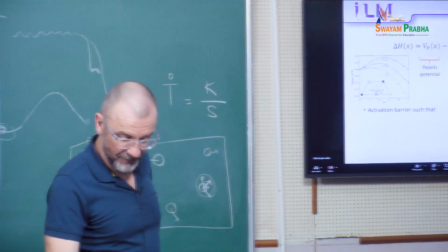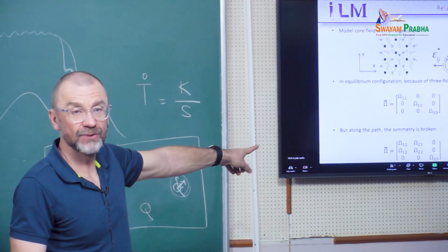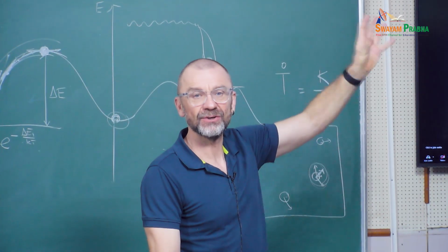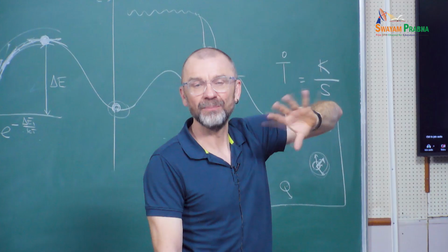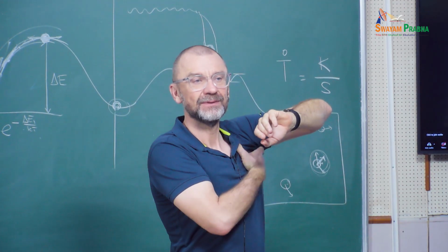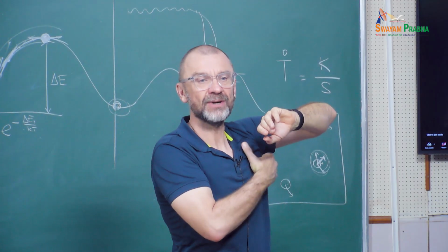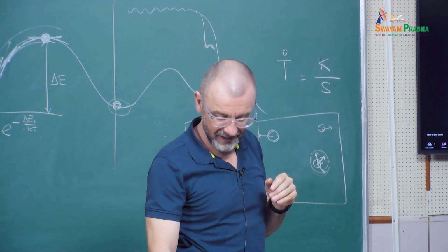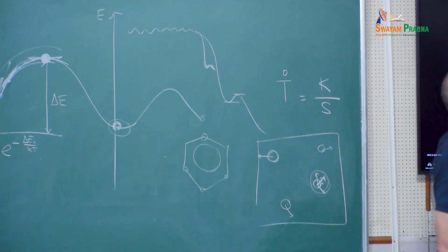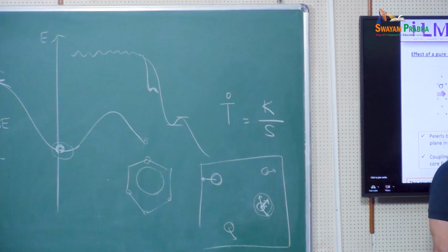And if we accept that we have such an eigenstrain tensor, how is this eigenstrain tensor coupled with the applied stress? If I know the eigenstrain tensor, how can I predict the effect on the energy barrier within elasticity?